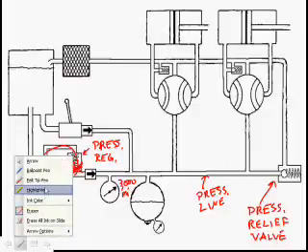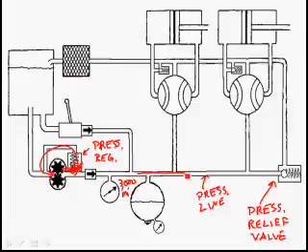Well, in that case, the pressure inside of the pressure line would go much, much higher than 3,000 psi, and things would start breaking. We'd have hydraulic leaks. It'd be a big mess. So this pressure relief valve over here is going to be set where the spring pressure is a little bit less. So this may be set to open up at, say, 3,300 psi.